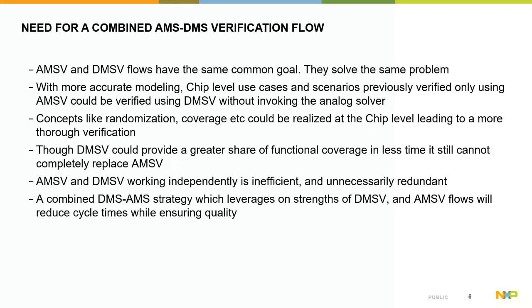Basically, we are trying to solve the same problem, which is trying to prove that the IC is functional at the chip level. And with more accurate modeling, with techniques like real number modeling as well as WReal models, the use cases and scenarios that were previously verified using only AMS, we could actually verify those now using DMS without actually using the analog solver.